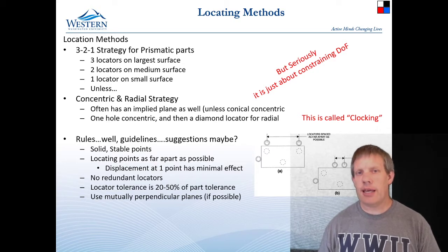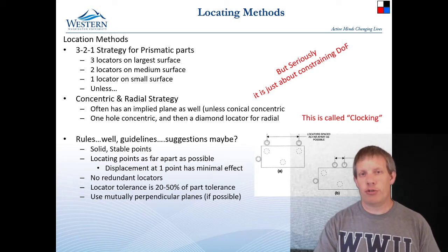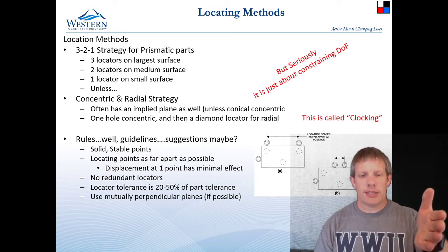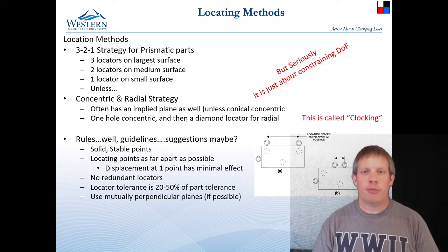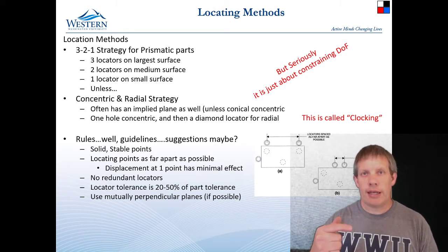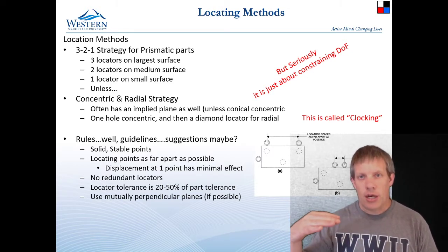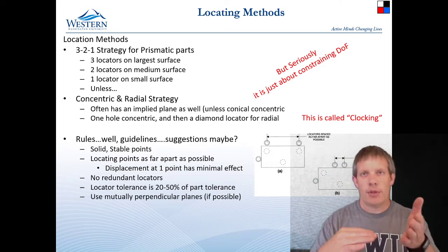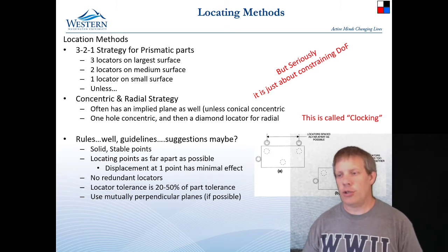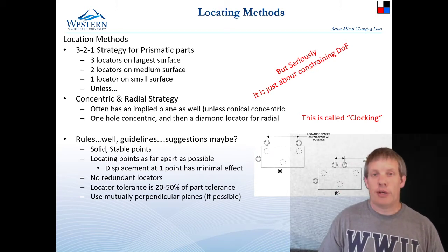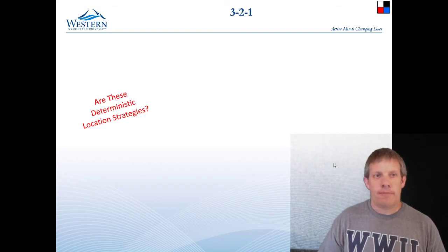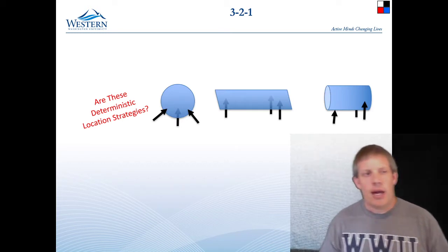And then finally, if possible, you want to locate it on mutually perpendicular planes. And the reason is because if I don't do it on mutually perpendicular planes and then I put my clamping force in, it will cause an additional force or moment up the non-orthogonal plane. And so mutually perpendicular planes whenever possible. Okay, so yeah, we'll talk about these briefly.